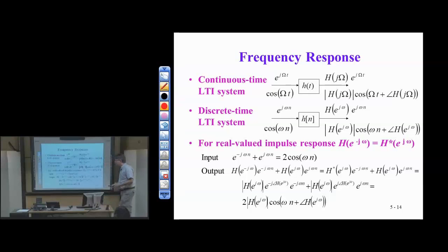So that's nice. Because I know what the answer is here from the fundamental theorem of linear systems, now I can use the additivity property of my linear system. So now I can put in a 2 cosine omega naught, and it's the same as putting in these two-sided complex sinusoids. This is a two-sided cosine for all n from minus infinity to infinity. Again, this is theory. We'll get to the practice. We're getting closer.